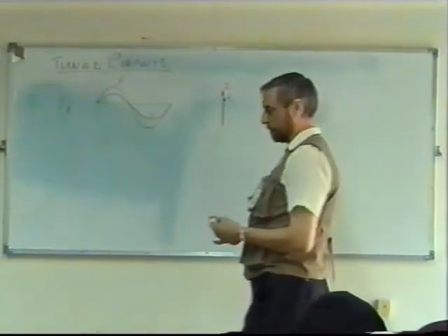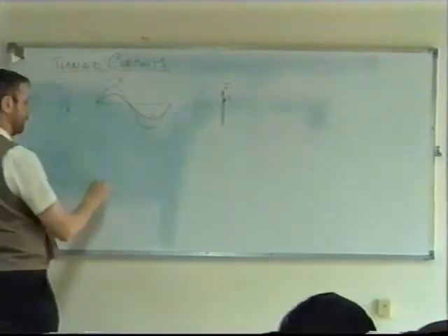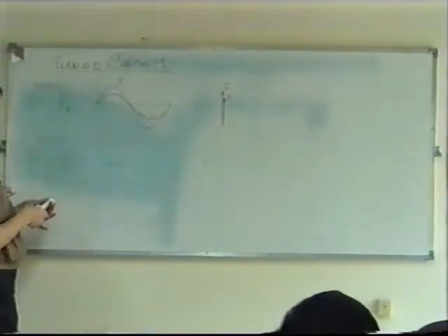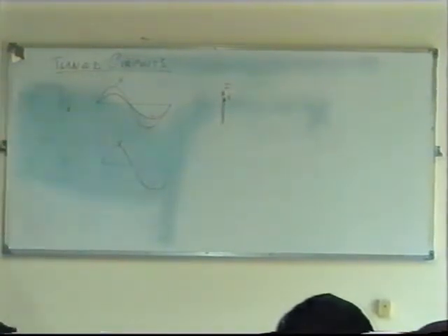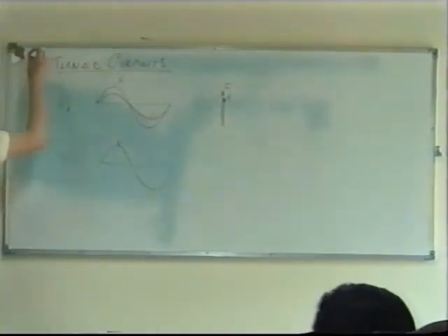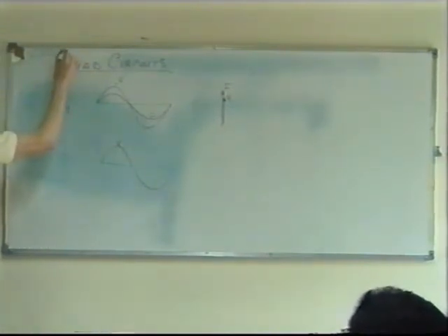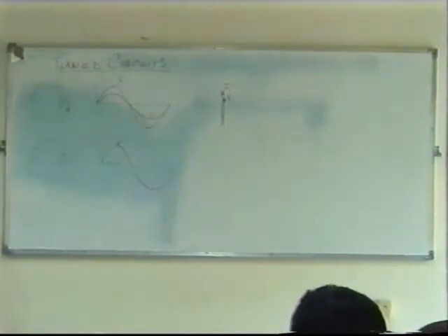Now let's have a look at a different component, a capacitor. In a capacitive circuit, again, we have an alternating voltage, and I can show that. This is V. But what can we say about the current through the capacitive circuit? Does voltage lead the current? No, not in a capacitive circuit. Yes, that's right, current leads. You can remember it by using CIVIL, can't you? Did you ever learn this? In a capacitive circuit, current leads voltage. In an inductive circuit, voltage comes before current.